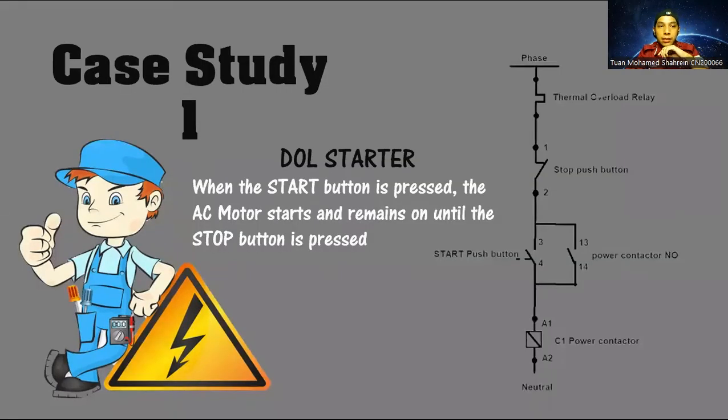Next is the case study. Case study one is the DOL starter. When the start button is pressed, the AC motor starts and remains on until the stop button is pressed.